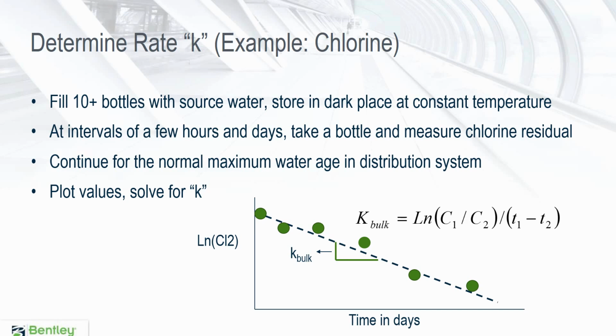You would get that, and that K value, you are then assuming that everything going on in the system that impacts that chlorine can be translated to that decay rate. This does get a little more complicated if you have blending of source waters, so you would then need to blend the source waters to see what that ultimate decay rate would be then too.